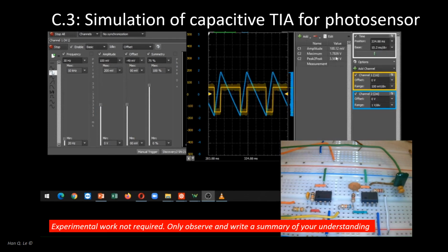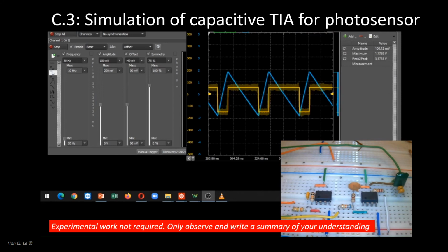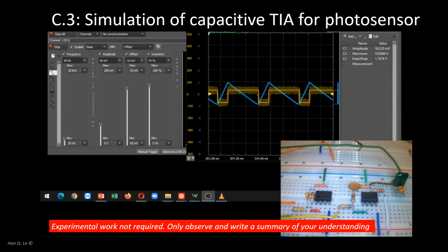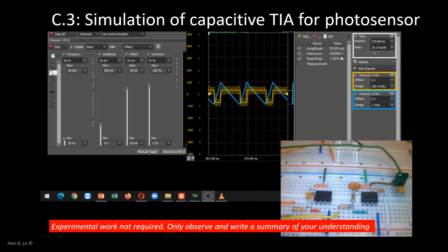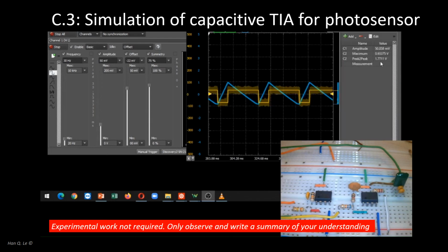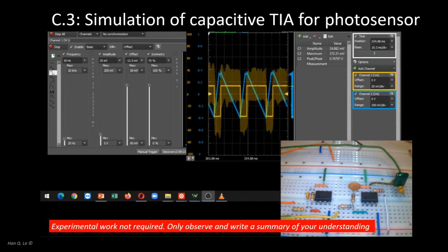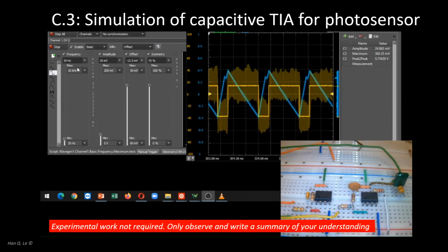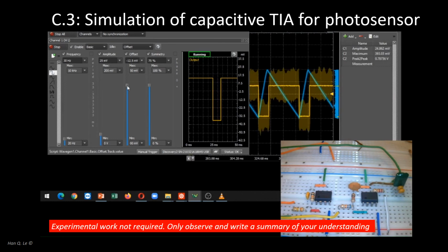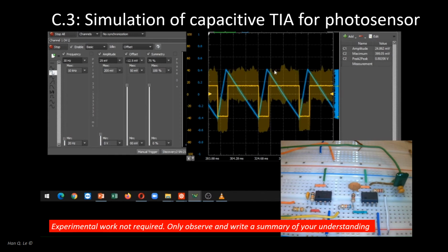The input amplitude is 100 mV. The output signal is 3.57 volt. The input amplitude is 50 mV. The output is 1.77 volt. When the DC level caused signal distortion, the offset was adjusted to avoid the error. It takes time for the adjustment to stabilize.